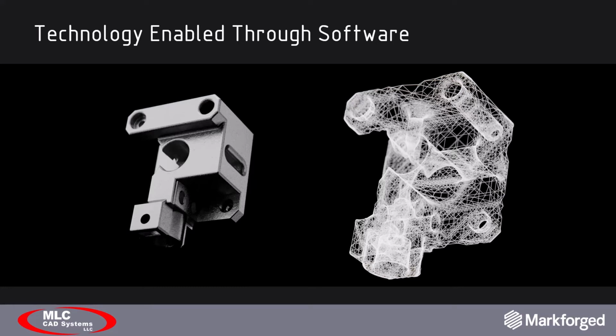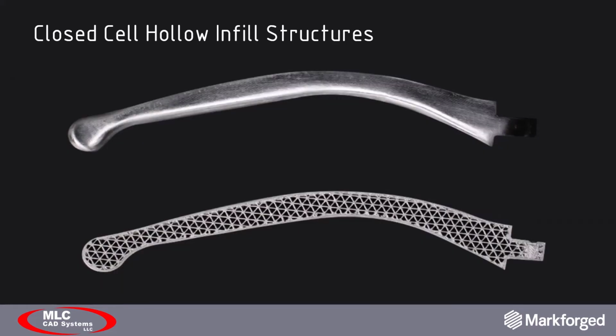The nature of the post-processing steps means that the part actually shrinks about 17 to 20% depending on the geometry. Eiger will calculate this for you by evaluating the centroids of mass and geometry of the part. The software innovations developed by Markforged to accurately predict this shrinkage is the real secret sauce to the process. And again, this was huge for Acme Audio because they didn't need to know anything special. The 3D printing technology took care of all of that for them.